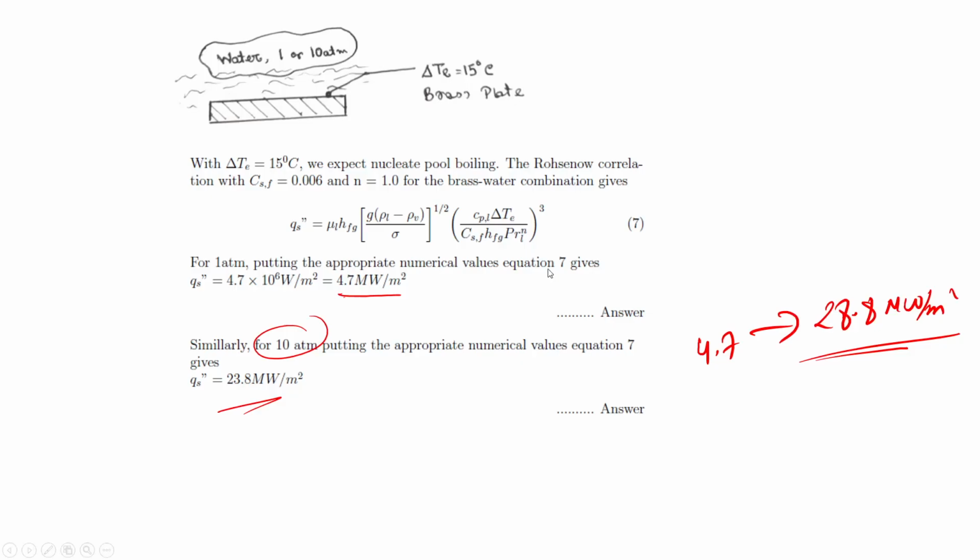So yes, those were all the questions related to boiling as well as free convection. So the main thing in these questions is you need to remember a few of these core formulas, and the Nusselt number correlations will be provided. Most of them is finding the overall heat transfer rate or heat flux or the power by finding the Rayleigh number, and then depending on the flow regime you need to use the Nusselt number correlation, and then eventually you can obtain the heat transfer coefficient from that and then find the value of power.